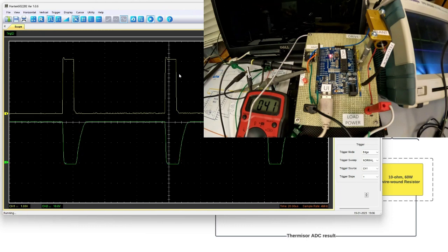For a DC signal, we could average it. If we're looking on the screen right now, and we said that yellow was, the way you read a scope, we're at 20 microseconds per large division. So 20, 40, 60, we're about 62 microseconds, and we're about 8, let's say 10 microseconds, so we're a little over 10% duty cycle. So we could look at the average power being dissipated within the resistor as 10% of the 20 volt supply, or 2 volts. I squared R loss through the resistor, or V squared over R, would be 4 over 10 ohms. So some tenths of a watt. And that represents what we're losing to the room.